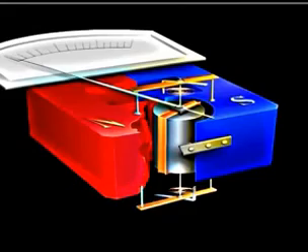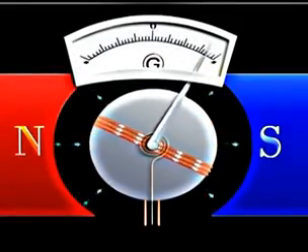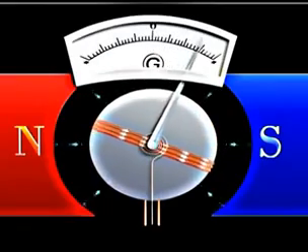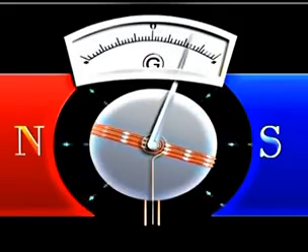The galvanometer is a current-detecting instrument. Here we see an application of the process shown in the kicking wire experiment. It consists of a copper coil wound on a light aluminum frame, pivoted in such a manner that the coil rotates in a radial magnetic field provided by 2 curved magnets.